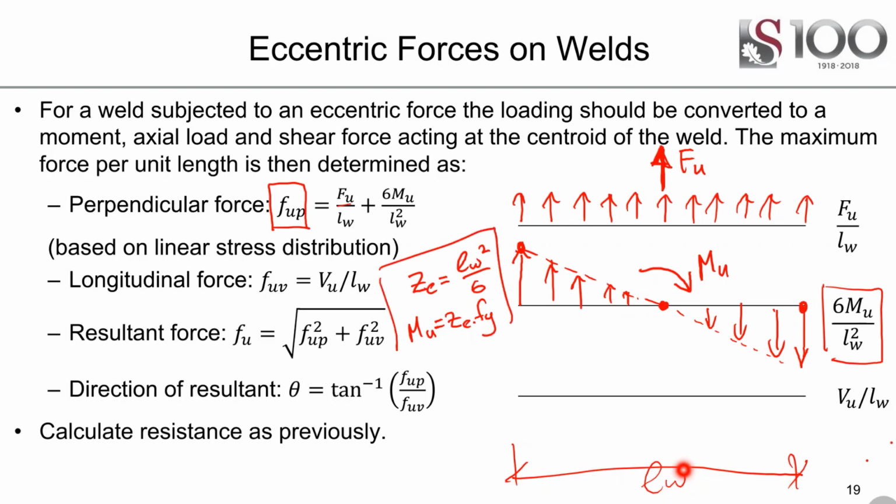I'm just taking you back to bending theory for beams, and that is where this would come from, because you've got a 1 millimeter wide weld, or a unit width, times L squared over 6, so that's an elastic modulus. An elastic modulus gives you the stress in an elastic distribution, and so we can convert then, well, we rearrange this equation, and we can then find the stress, which is 6 Mu over LW squared.